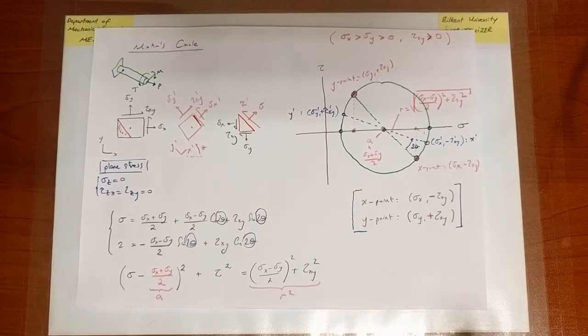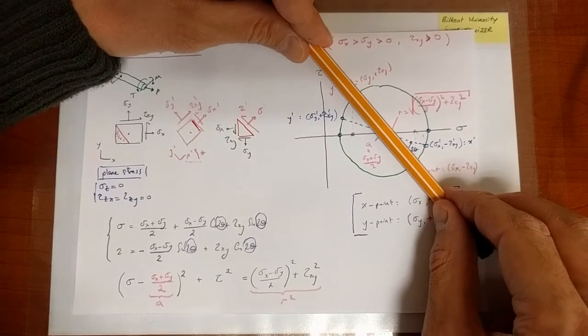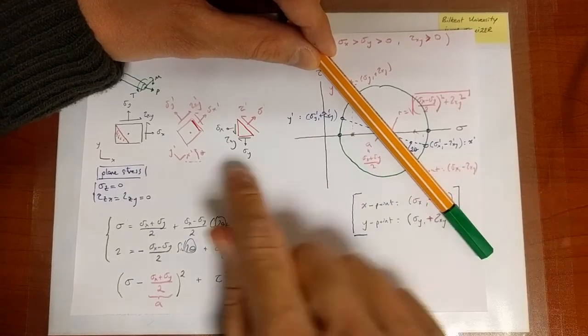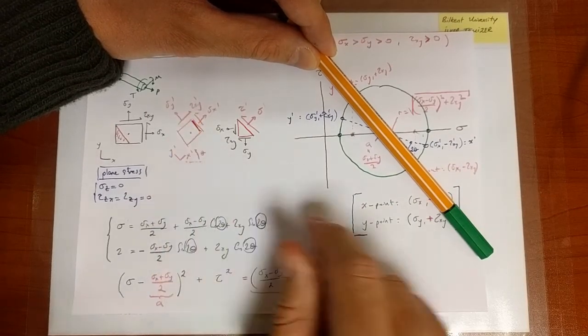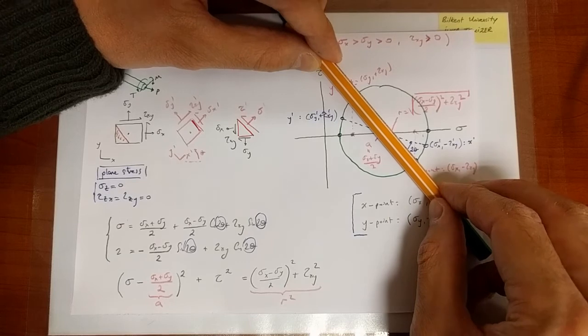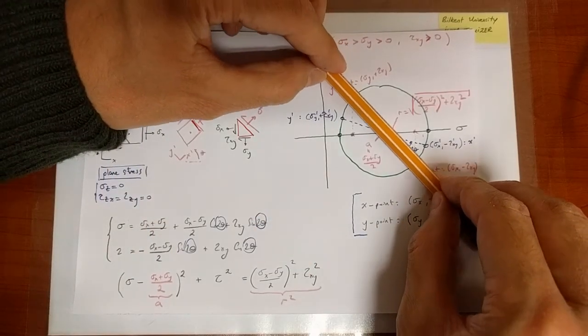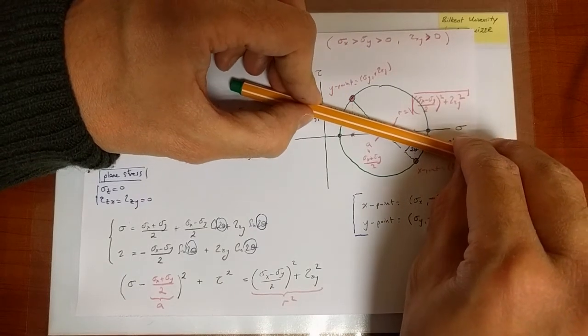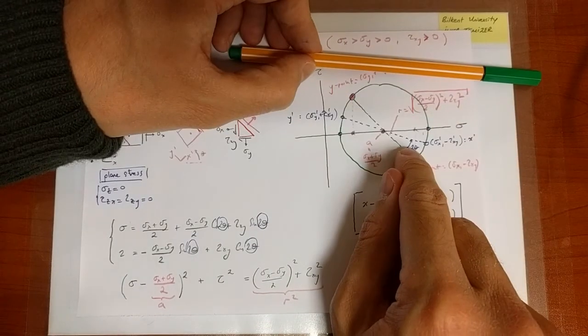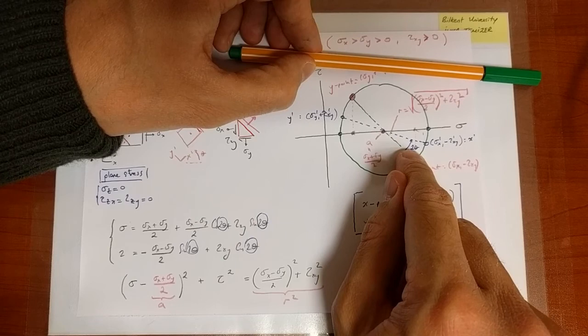in our Mohr circle. So now what our Mohr circle is able to give us is, you start from the original picture and you can determine the components of the stress with respect to a rotated picture for the same state of stress, just a rotated picture, by doing a corresponding rotation on the Mohr circle, but that rotation is just twice as much.